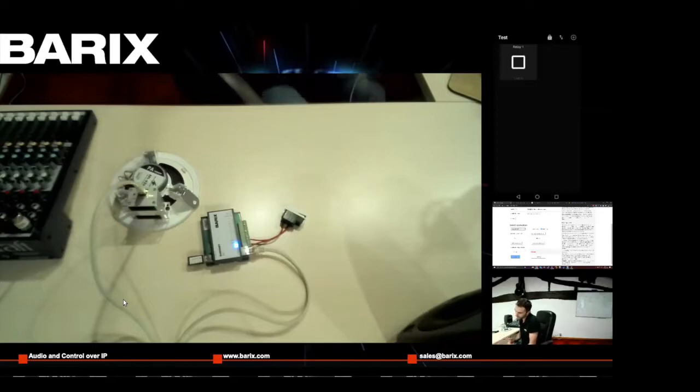And I made a very simple and basic example here to activate the relay. When I press the relay button that you see on the screen on the top right corner, I will trigger the activation of the relay on my Barionet, passing through an MQTT broker.